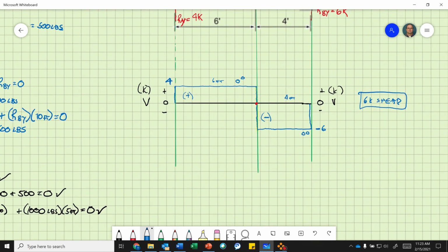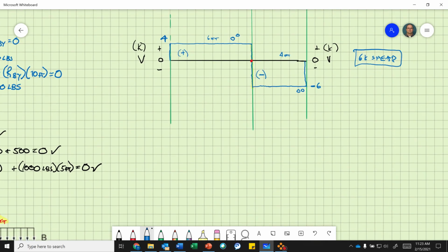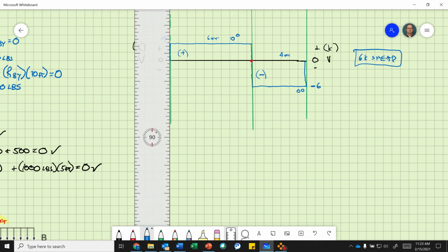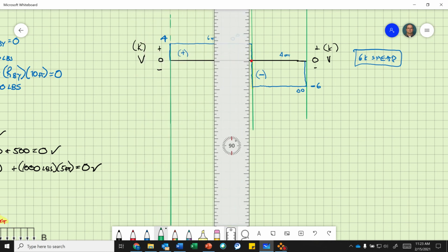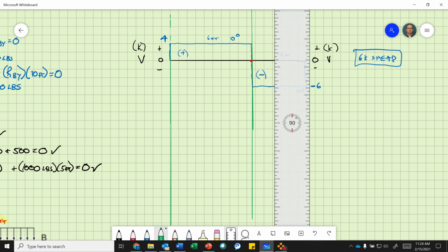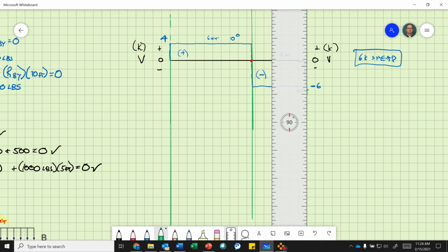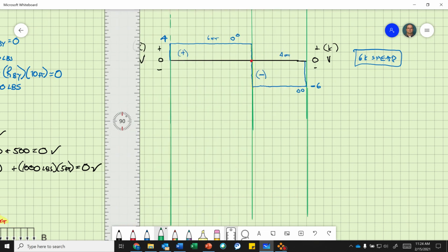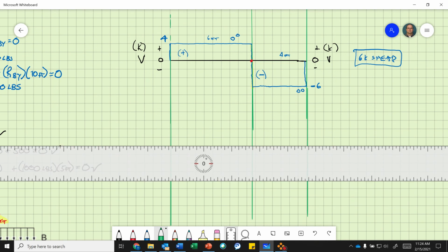Okay, now let's do the moment diagram. So moment diagram, okay, I just keep projecting my lines down. Right below, so points of 0 shear, beginning and end of line distributed loads, where your reactions are. Okay, just project that down. Okay, and now I need to draw a moment curve.